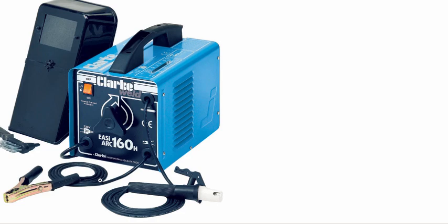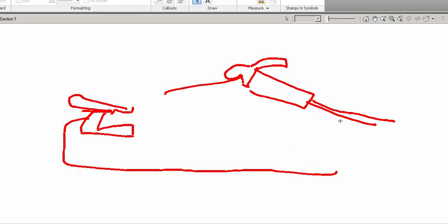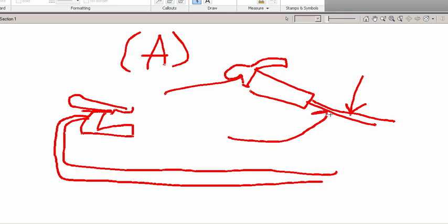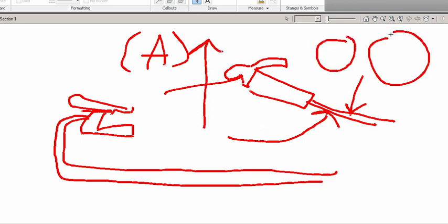In some of the welders you may have seen, these wires can get much larger, and they can get nice and thick. What controls the thickness? Well, there's a couple things. First of all, the amount of amperage that the machine can put out controls what size of conductors you have. Because if you have a lot of amperage, you need bigger and bigger conductors. Small amounts of amperage do not need large conductors.